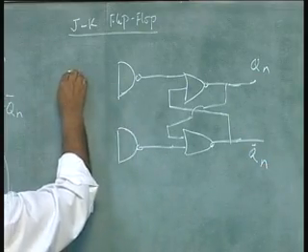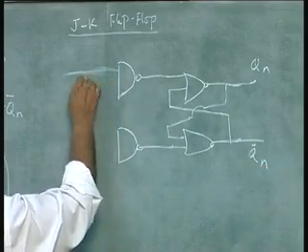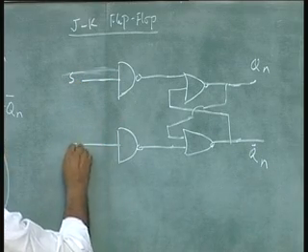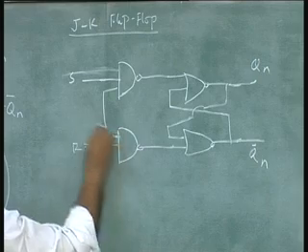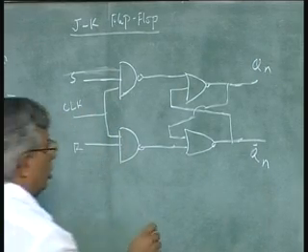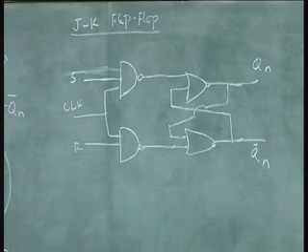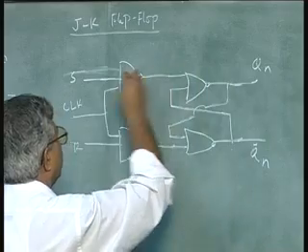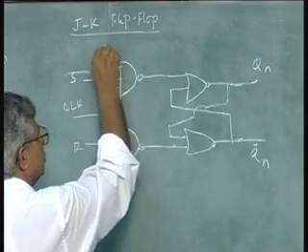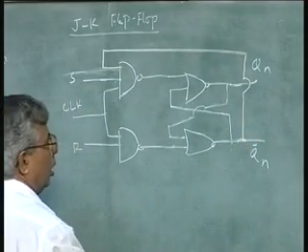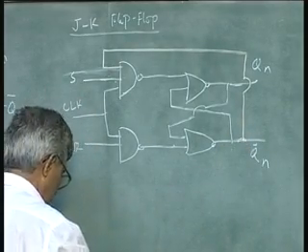This is my S, R, clock. What I am going to do is take the output of this Qn and connect it to this input, Qn bar and connect it to this input.